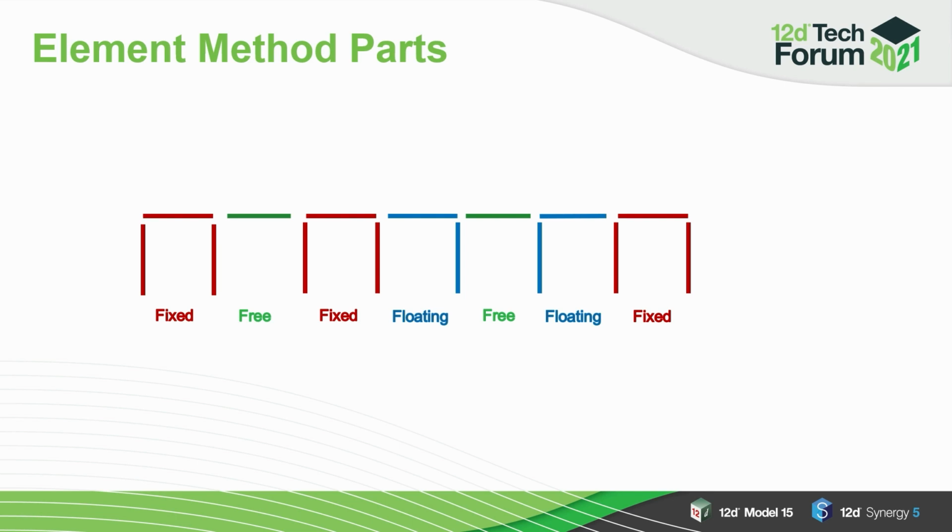And then a free element part is like a tabletop. So it requires legs from element parts on either side of it to be able to stand and to be able to define geometry. So I'm not going to overdo this analogy too much, but how this is going to help us is just to initially help determine which element parts we'll use when we're creating our superalignment. So before we create the geometry, we can plan out which element parts we're going to use and where. So let's jump into 12D.